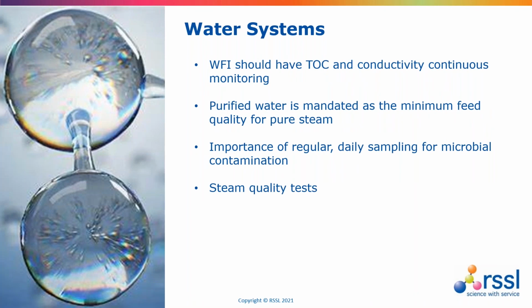There is also reference about water sampling to make sure that worst case sampling points are always included, things like the end of distribution loop returns, and that there must be water sampling taking place every day of manufacturing. So it doesn't necessarily need to be every point, and that becomes impractical for larger facilities, but there needs to be some level of sampling taking place as the water system is being used.